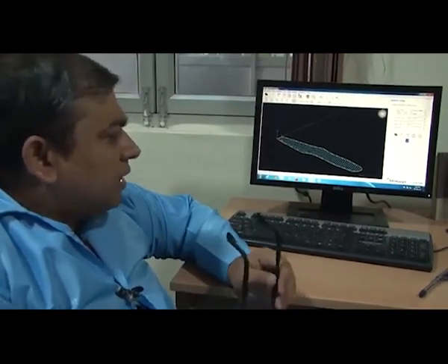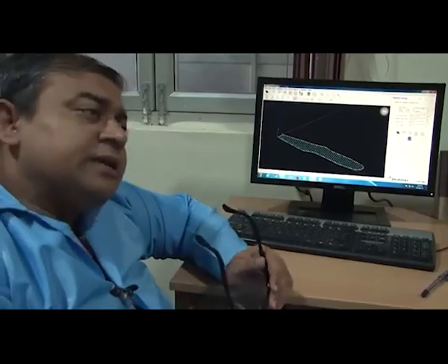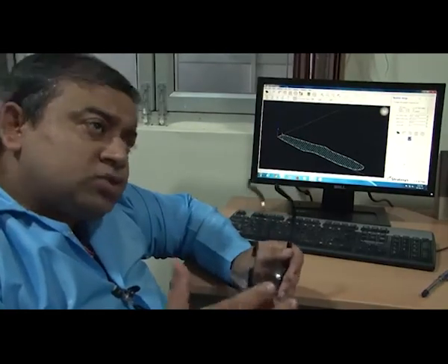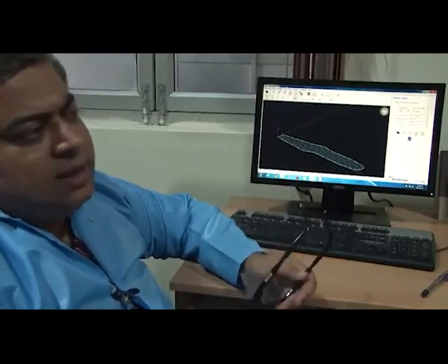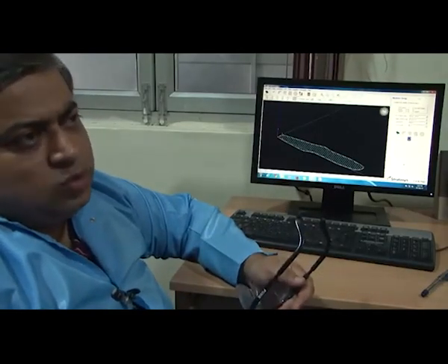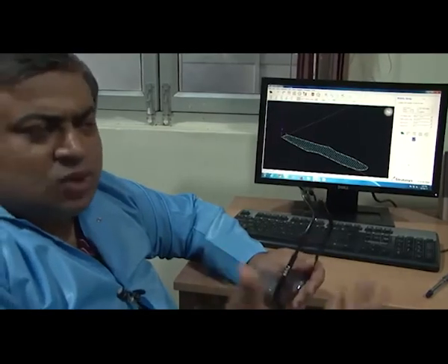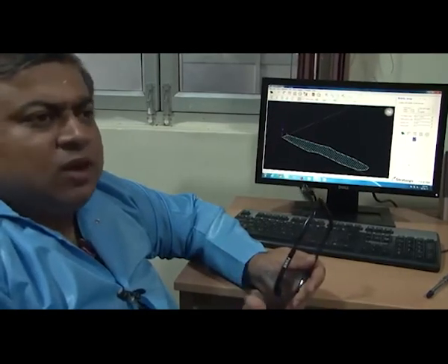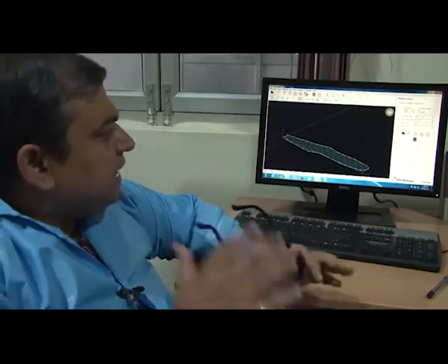see or give the support structure of the material. And once the support structure is also defined, then we do the tool path. So once the tool path is planned, as you saw, the material had a denser tool path than the support structure, which means that the support was much less material, just only intended to support the material, which would be parted away later as non-useful material. Once this is done, the file is complete.